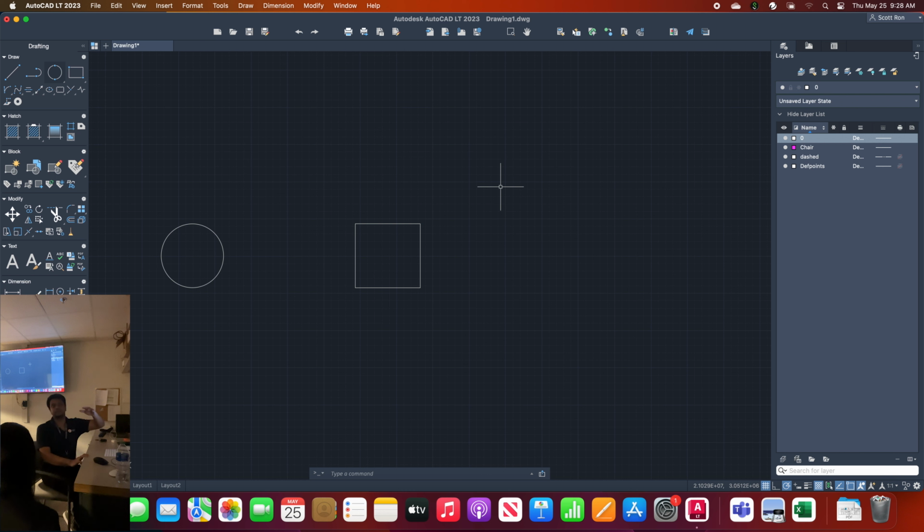Let's say you're trying to express certain staircase lines that go through consistently everywhere. Just use a construction line to show your references. You can delete them. Once you make your drawing and you know everything is in proper dimension, you can delete the construction lines afterwards if you don't need them.